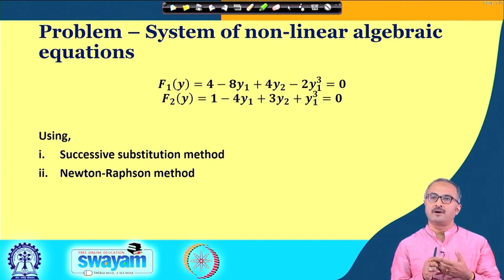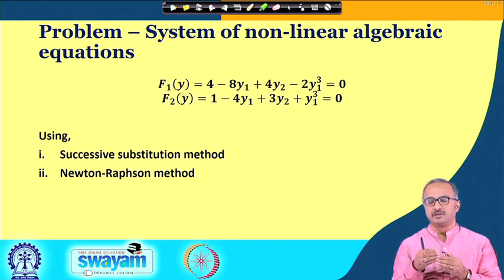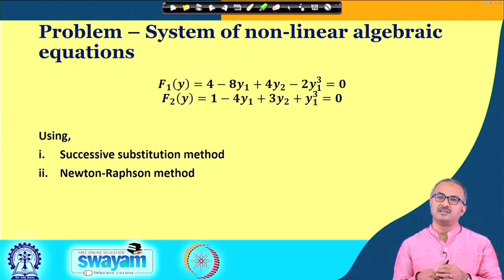Again, in the momentum balance equation you may find the various properties which you are using may be varying with the temperature. So, you need to know temperature at each time instant, and those temperatures should be obtained from the energy balance equation. In similar fashion, you may also find some dependency of the momentum or the energy or enthalpy on the composition of the particular system, and the composition itself again will be dependent on the velocity profile or the temperature profile in the system.